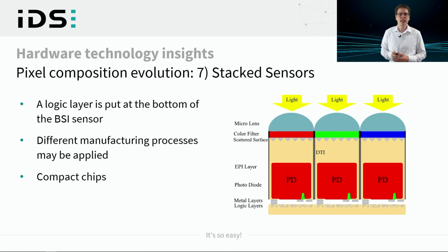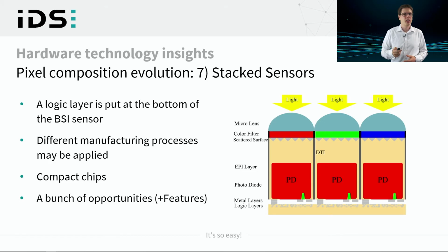The previously necessary logic of the ADC, the timing and the digital processing units placed around the active imaging array can be put in the additional logic chip below, and even more in terms of features on pixel level or sensor level are possible. Thus, the sensor chip gets smaller and, remember, this lowers the production cost of the image array chip.